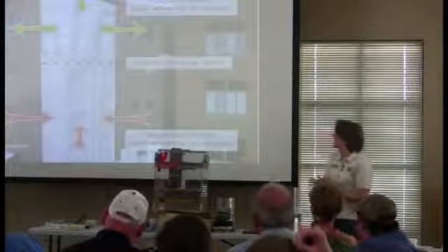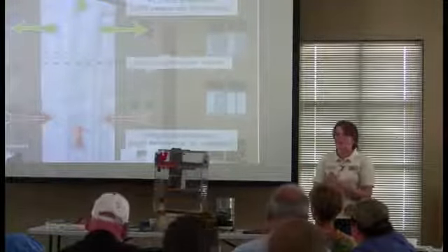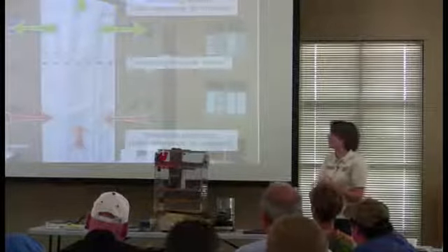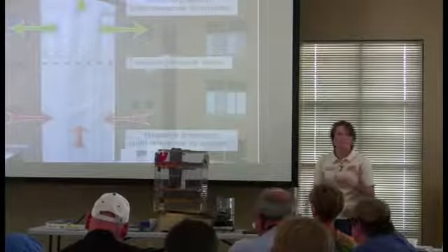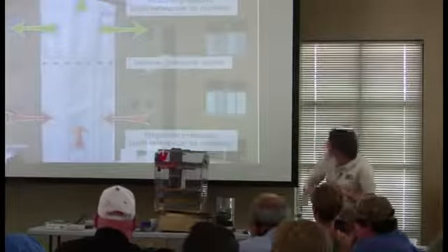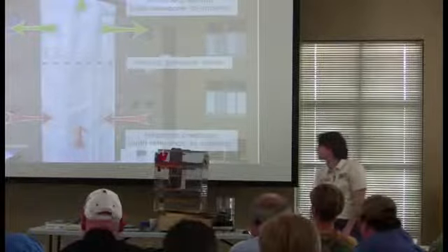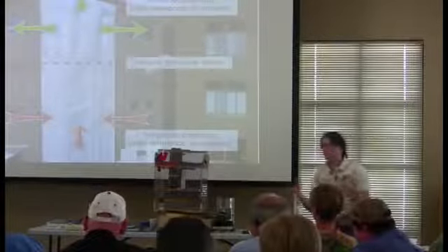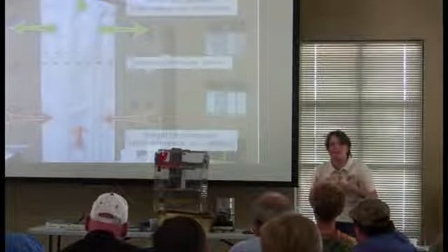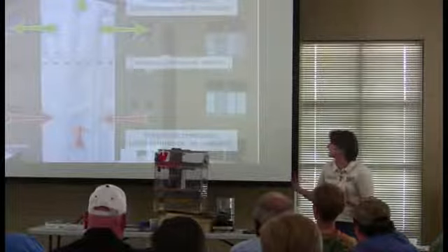And so we have an actual picture of it, which is great, right? Not always do you get to see building science in a picture. This is actually a renovation on a multifamily building, and right now we have some, let's just call it poly, on the outside that's sealed. It's like house wrap, basically. House wrap. Yeah. But we can see at the bottom, what is that house wrap doing? Is it going out or being sucked in? It's being sucked in. It has that negative pressure, and it's really being sucked in at the very bottom.